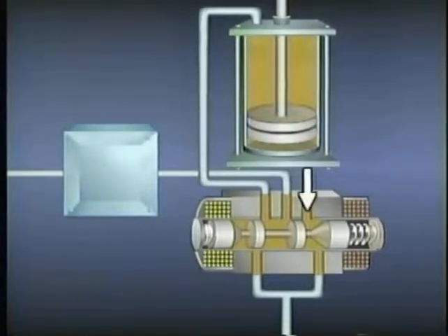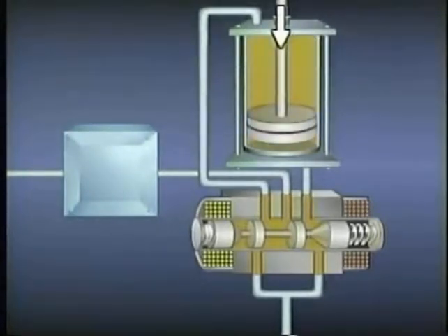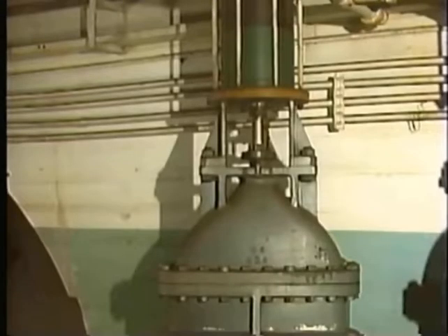The fluid returning from the actuator is controlled only by the movement of the actuator. Because of that, a heavy load that exerts a force in the same direction as actuator movement could cause the piston to move at an uncontrolled speed. This would cause the load on the actuator to run away. So the meter-in method is suited for applications such as operating this valve.